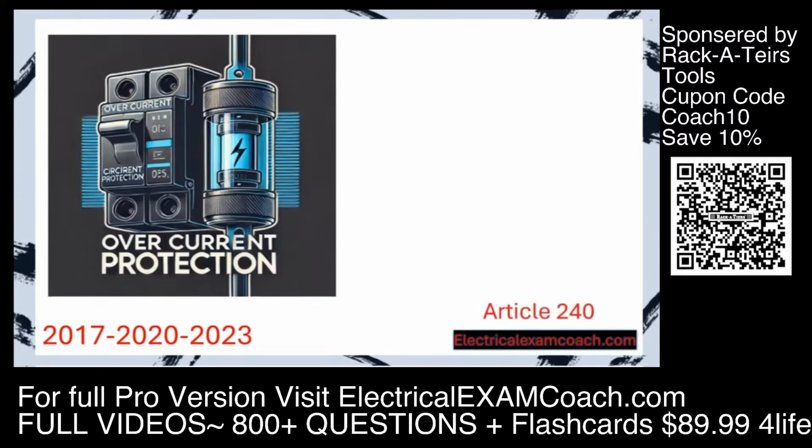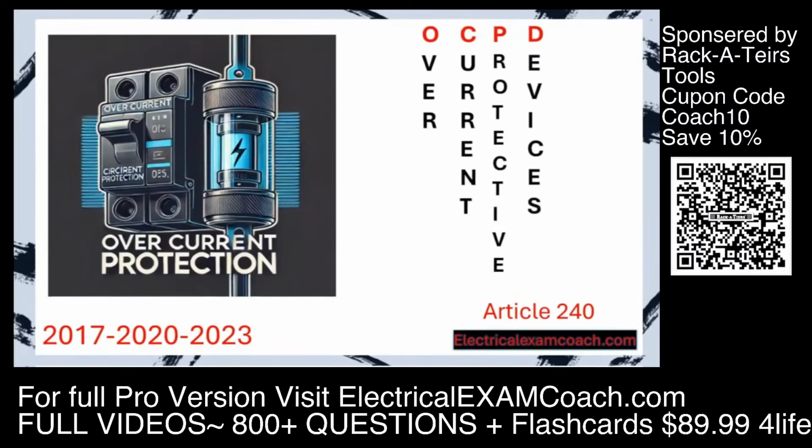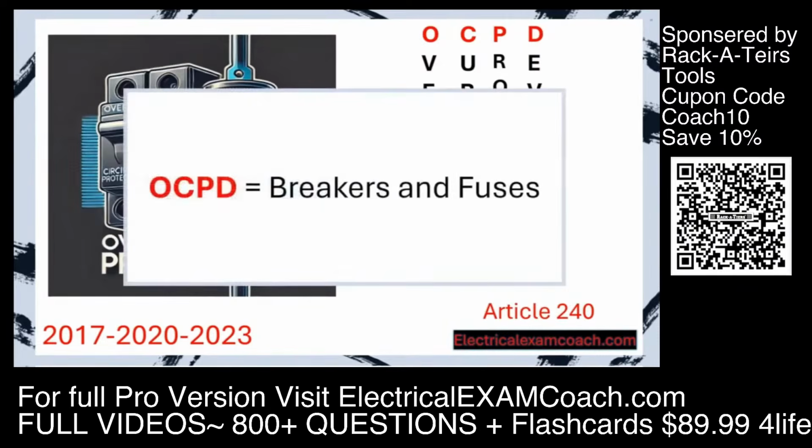We're going to be in Article 240, and we're going to be learning all about overcurrent protective devices. You'll hear me use the term OCPD throughout the rest of the program, and all it stands for is overcurrent protective devices. But to simplify it even further, just think about it like this. Anytime you see OCPD, it just means breakers and fuses. Whether it's the individual breaker at a branch circuit, 20 amp, or a 100 amp feeder breaker, or our main 200 amp disconnect, it's either going to be a breaker or fuse, and they're all OCPD.